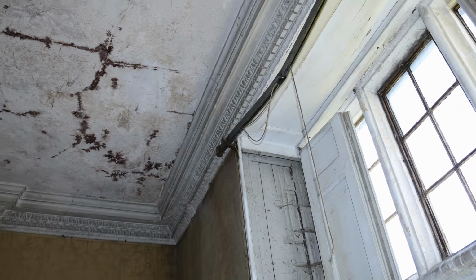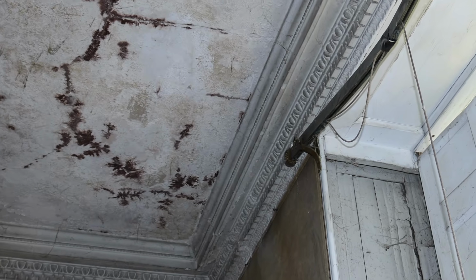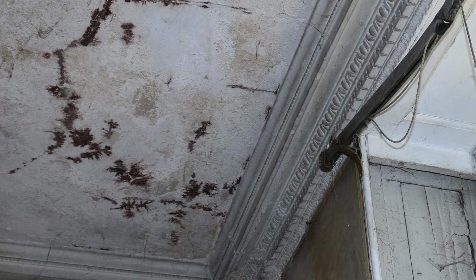So if you're suspicious, then you call in someone to independently assess what is really going on, where the problems lie. And then finally, and I'll shut up after this one, the final thing is to actually look for the mycelium, the little growth, the fibrous roots that start to come out. If you start seeing little fibers, like black cotton, a little like lacy black cotton creeping across the face of a timber, that could be an indication.